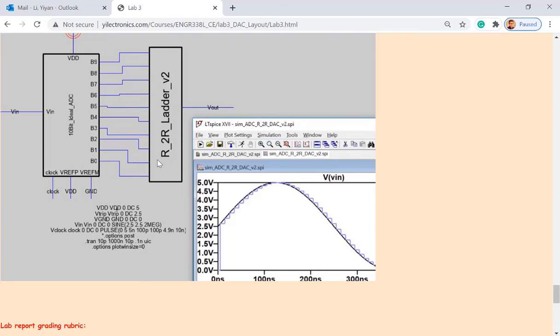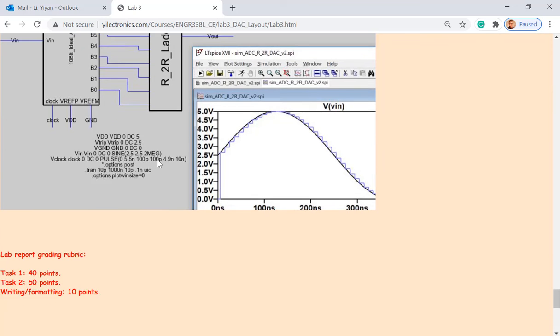The EDA software only extracts the electrical netlist, so it's actually just reporting all these nodes. It's the same electrical netlist for the schematic and the layout, so it doesn't matter which one you are going to simulate.